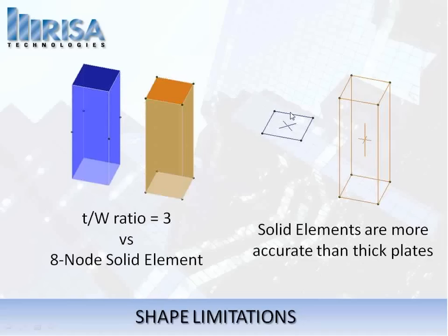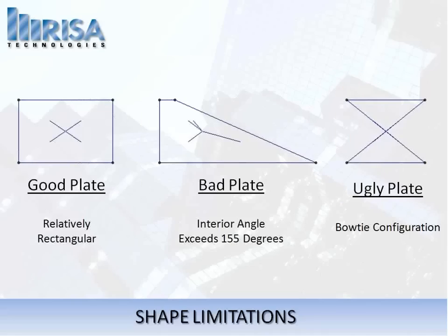So in the case of solids, doing a design of something that plates could be used for would be very difficult. Although in order to get the correct stiffness and load attribution, if you have very thick elements you're trying to model, say a deep concrete beam that's maybe only spanning 3 times its depth, something like a solid element may make sense in that case. But we're not really going to delve into those too much within the context of this webinar. It is something you can look up in our help file to learn more about, though.